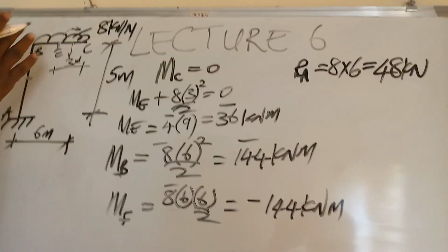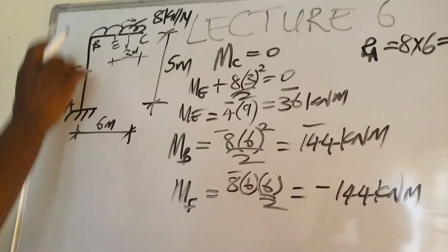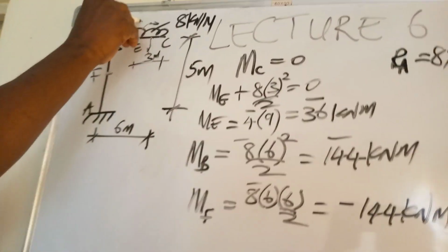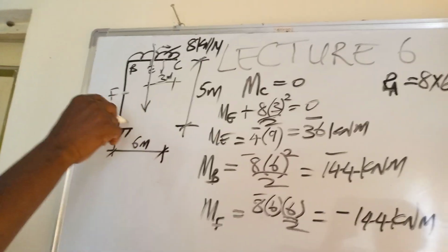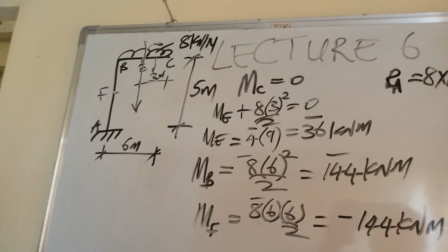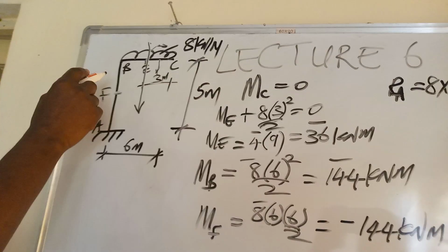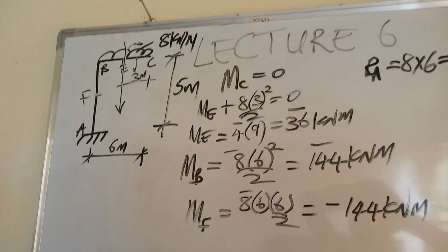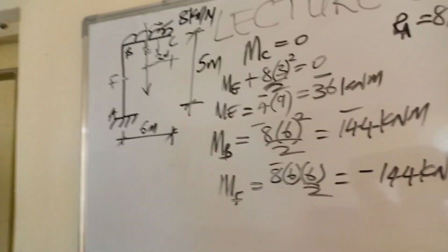That is the area, the length, half of this length, the force. If you watch the line of action of the force, look at the arrow I'm drawing. The line of action of the force is parallel to BA or BF. So it cannot multiply the distance BF or BA to get moment, because that distance BA or BF is not perpendicular to the load.